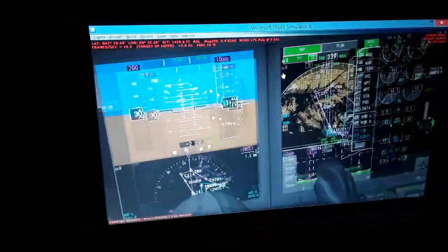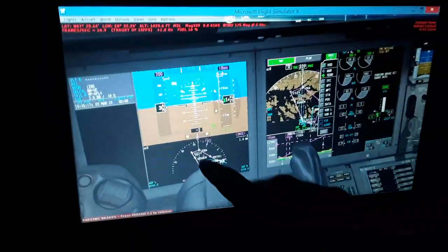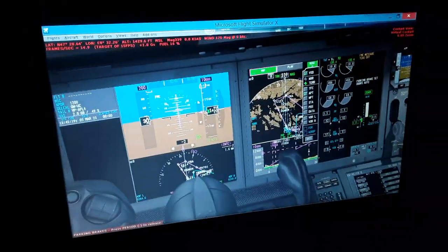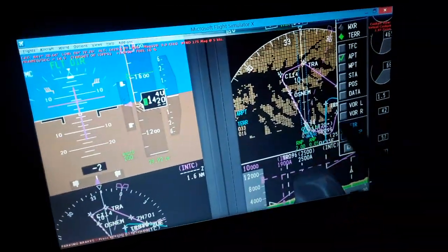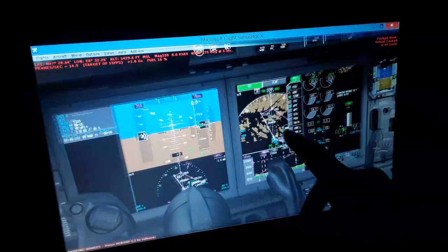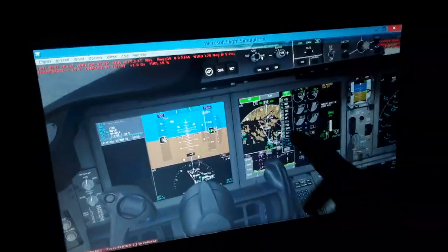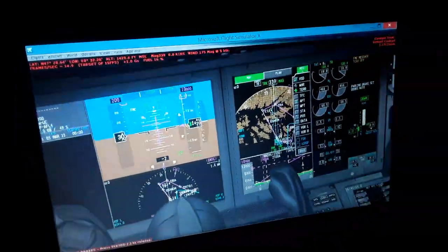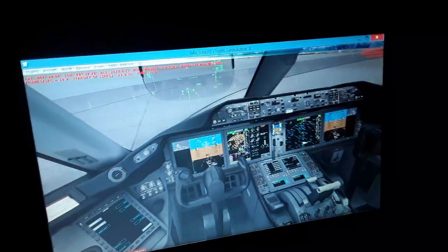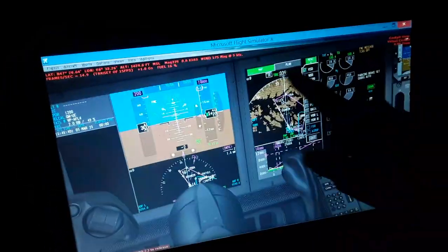integrated flight plan. You can see the flight plan, which is integrated into the horizontal situation indicator. Below, we have to follow the purple or magenta line during the flight from takeoff over here using this runway. We're going to climb through these waypoints and then come back for landing. So we have also the vertical profile of the navigation. We have the horizontal and vertical navigation display here.